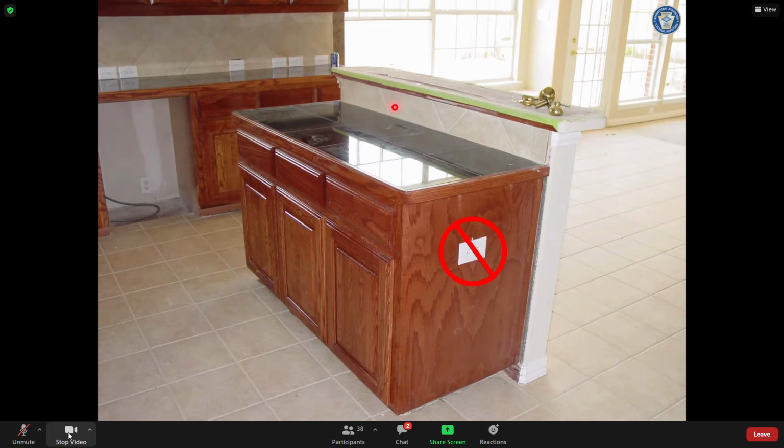So if I scoot it over to where I'm less than 24 inches to that point, then now I'm 40 inches to that point. So it would actually take 2 receptacle outlets up here to make this code compliant under the 2017 NEC, 2018 IRC.